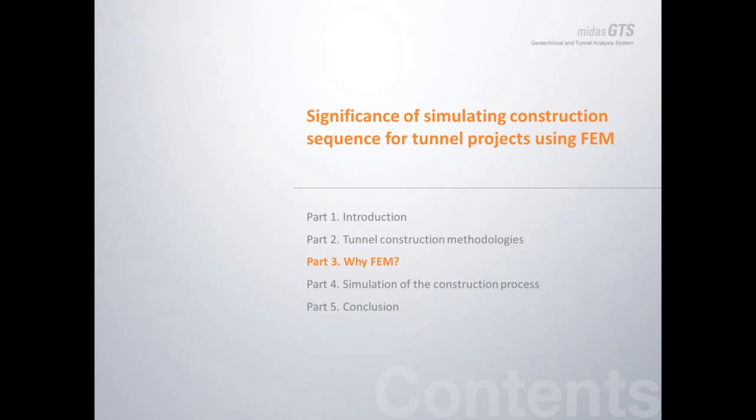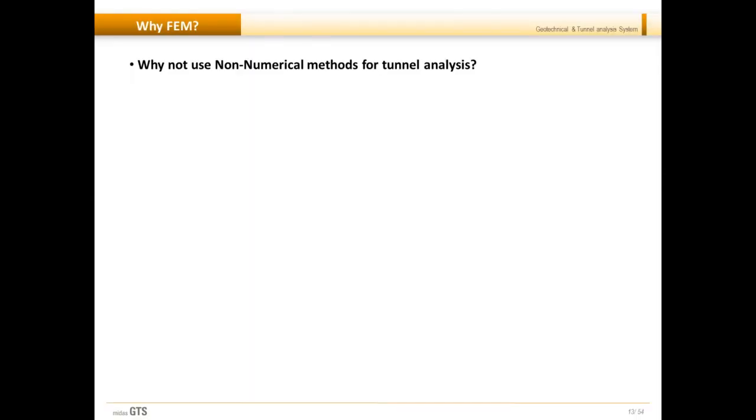Alright, so now let's see why finite element methodology is used to simulate these tunnel constructions, or why finite element analysis is needed in the first place. Well, this is the first question that every time we are talking to engineers who are looking at finite element methodologies for the first time, they ask us, because there are so many non-numerical ways of obtaining good predictions of the likely ground response to the tunneling and the likely loads in the tunnel lining.